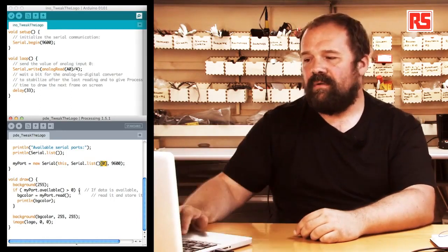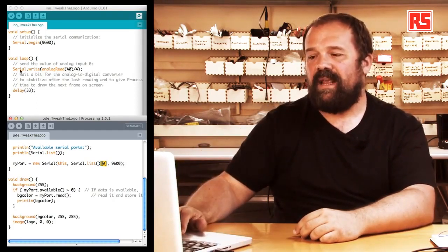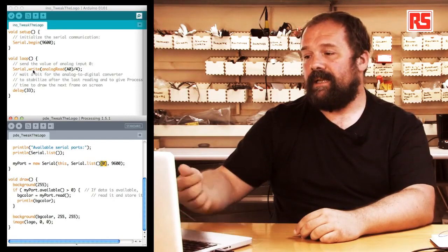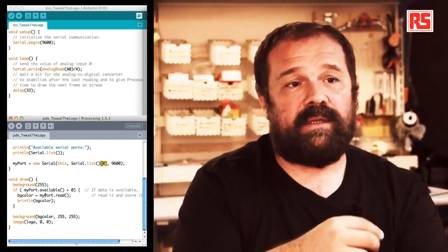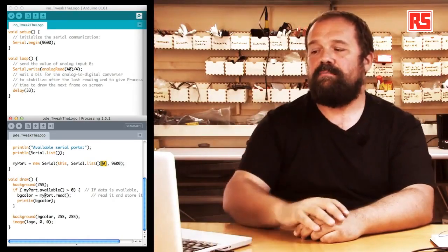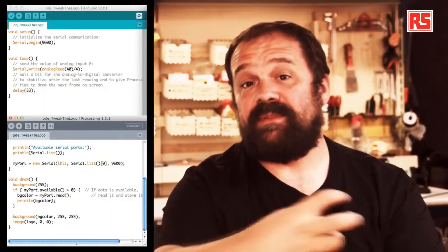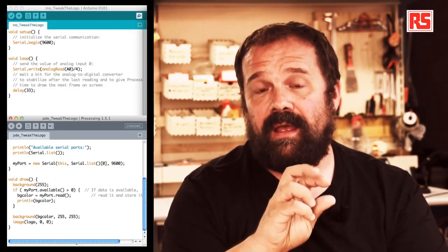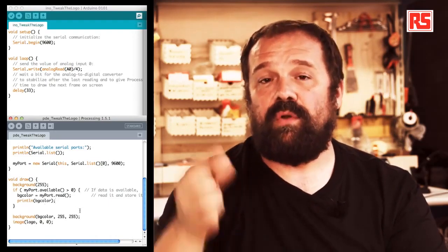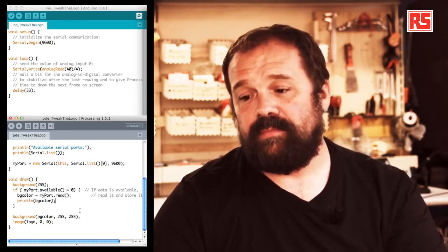So you can see now, by looking at the code side by side, on the Arduino side, we have serial.write that sends the data. And then on the processing side, we have myPort.read that reads the same number into the bgcolor variable. After reading the value that comes from the Arduino into the bgcolor variable, we use println(bgcolor) to print the value contained inside bgcolor at the bottom of the processing IDE window.